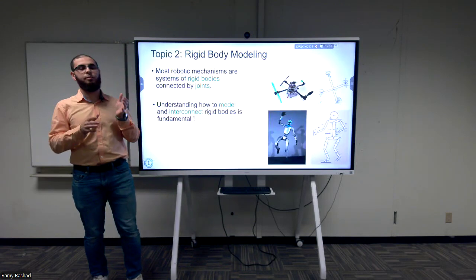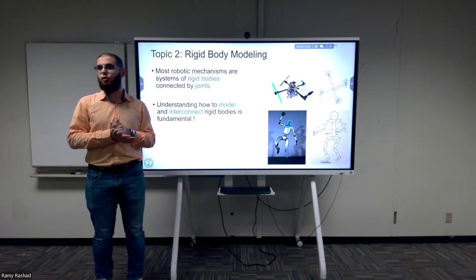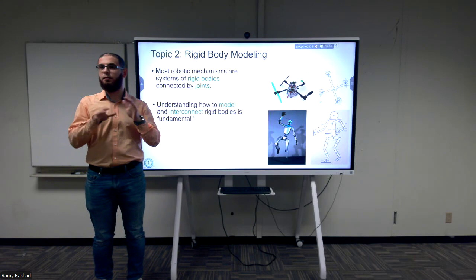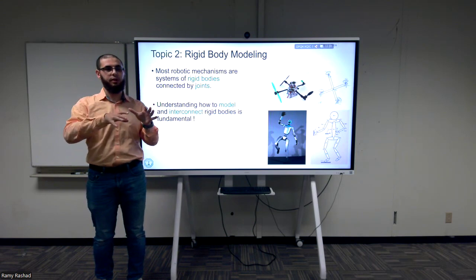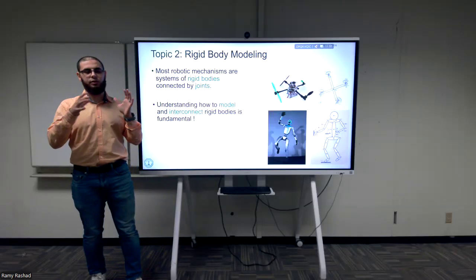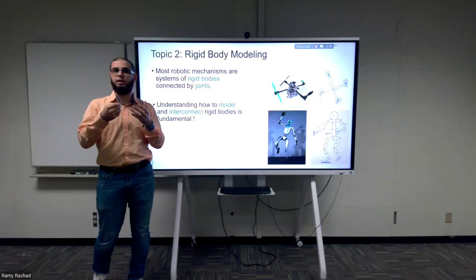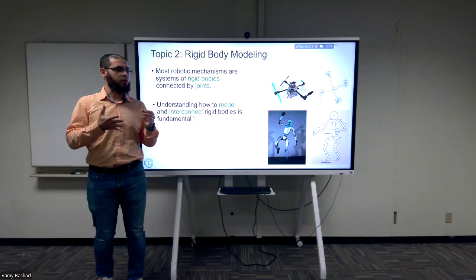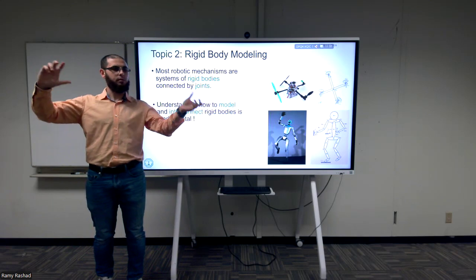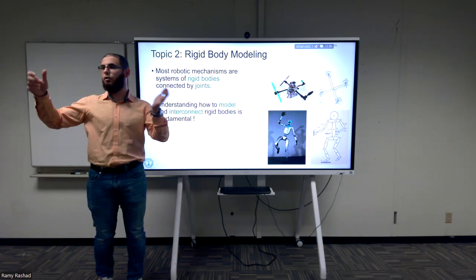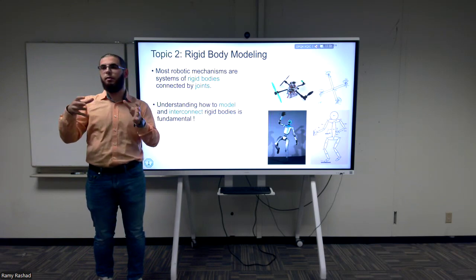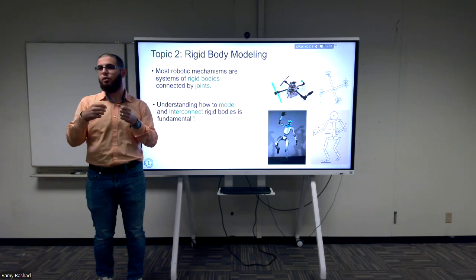The application part, which is what we're interested in the course, is robotics. Robots or robotic mechanisms, unless otherwise stated, we assume that they are just rigid bodies connected together through joints, and that's it. I will not say any, but the majority of the stuff that we're interested in, so that includes humanoid robots, that includes multi-rotary UAVs, even if the propellers are moving all over the place and they are variable tilting, then we can model them with rigid bodies connected together through joints.